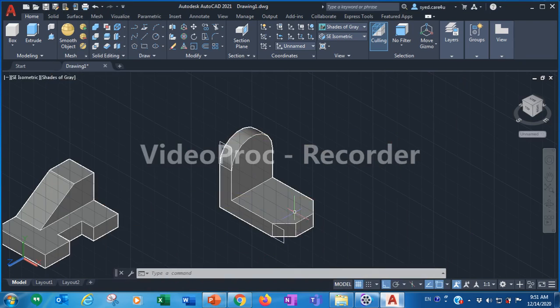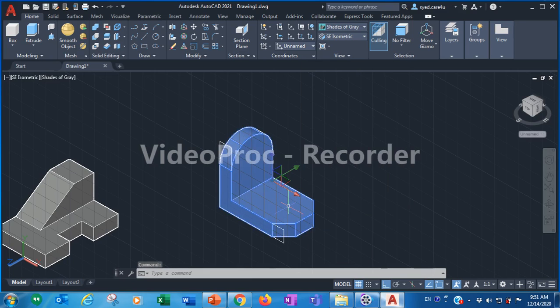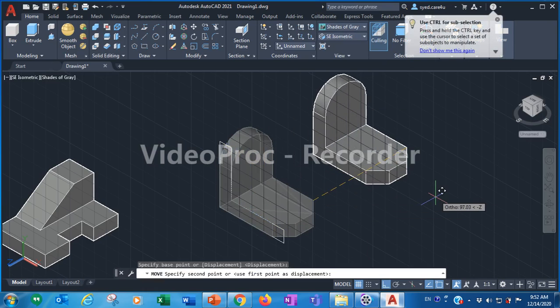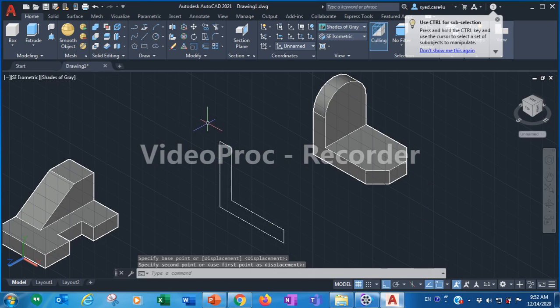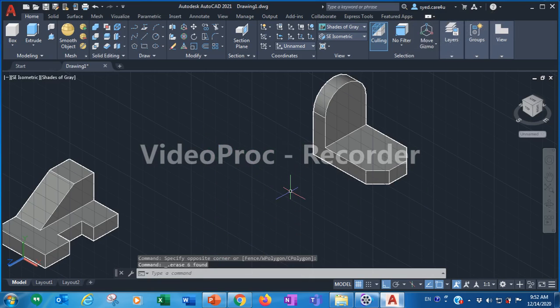So before doing that, okay, let's move this and delete the 2D construction lines. So click on this figure, right click. Okay, first click on this figure, right click, select move and move this figure. So now the construction lines will appear. So select all the construction lines and press delete. Again move it back.